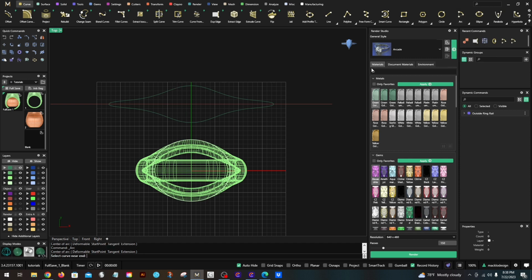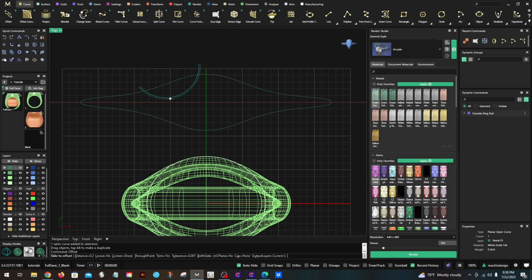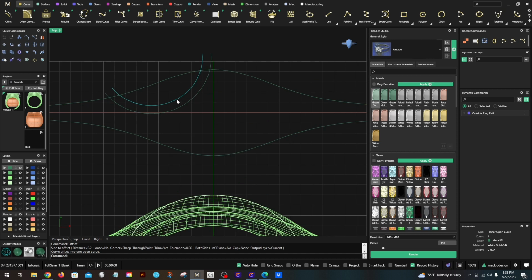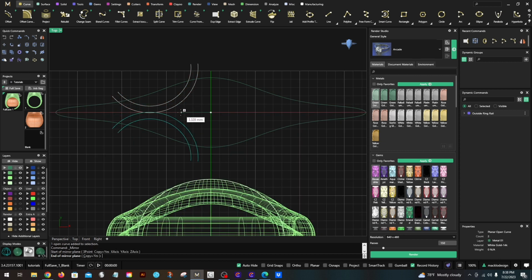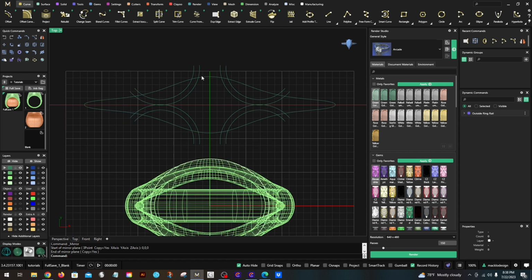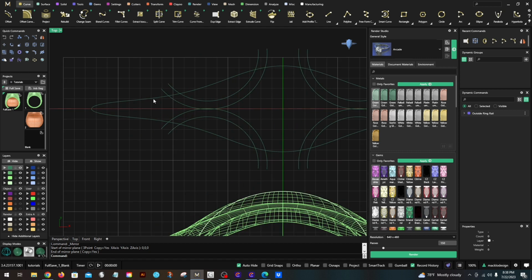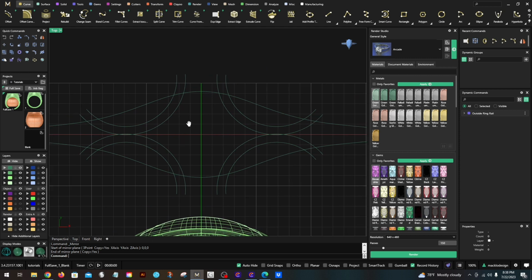And sometimes I just play. I don't always have anything in mind, and I will just do a curve and offset it, and usually by 0.8 is a nice offset if you want a substantial curve. All right, and then I just play around and I'll mirror it, and then you want your center to be somewhere on that line. This can be F4 for your center. That's kind of nice. You can leave this open down here because it's not a very deep one.